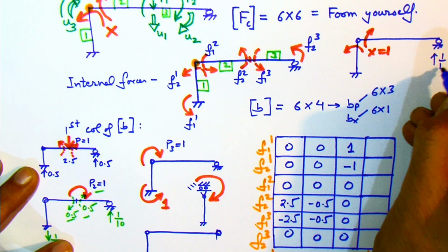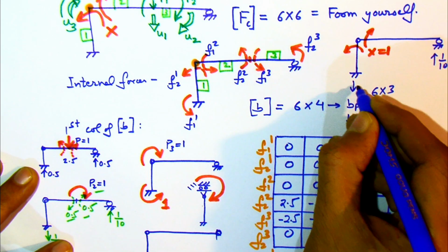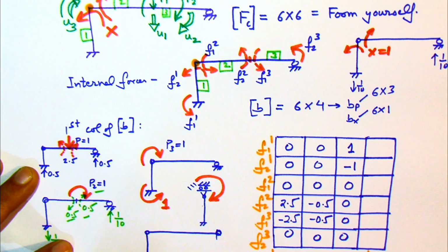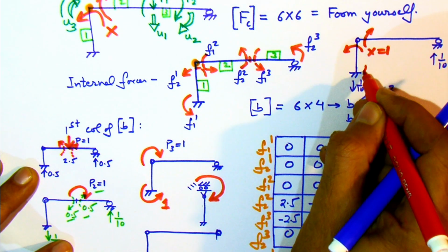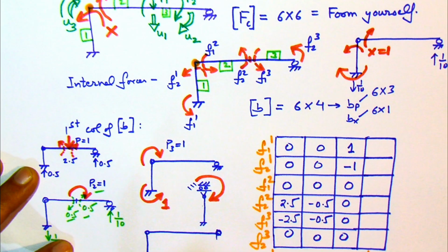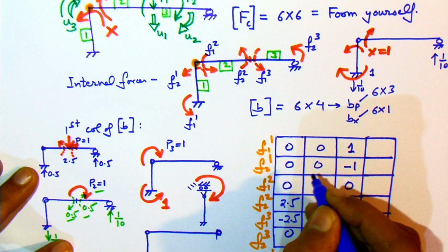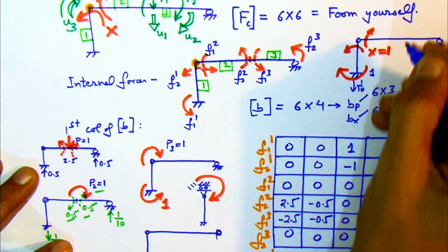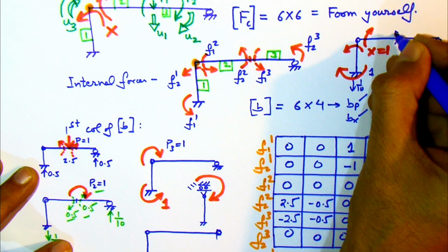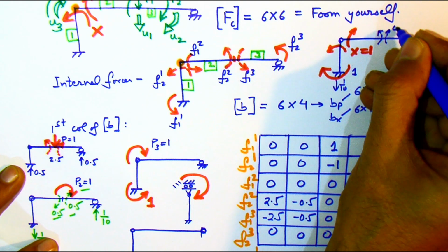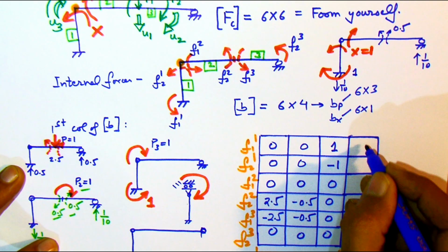So we can analyze both the parts and find the internal forces at the desired locations by just equilibrium, and the answer we write in the form of the components of the B matrix. So this is now Px. So this way we have formed the B matrix also.